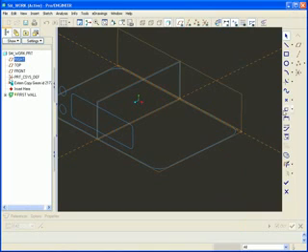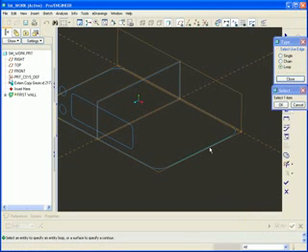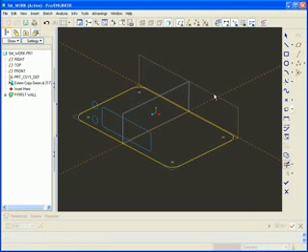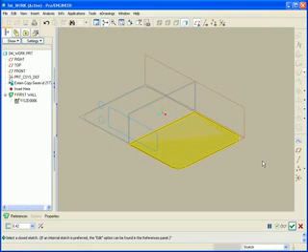So let's use Edge now. In this case, we'll use a loop picking up all the curves for the entire plan form. Now since this model happens to be symmetrical and we want to keep this tutorial somewhat short, we're only going to build half of it, and we'll utilize the mirror command as well. Need to use the squiggle trim tool to pull off half of it, and then because it's a flat wall it needs to be a closed sketch, and so we'll drop that closed.